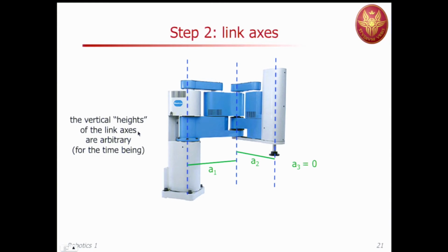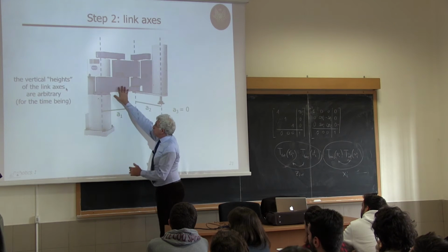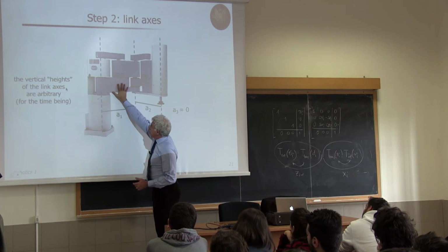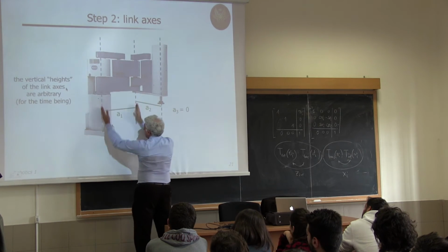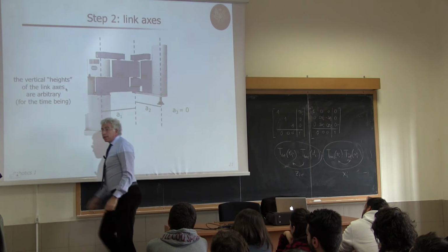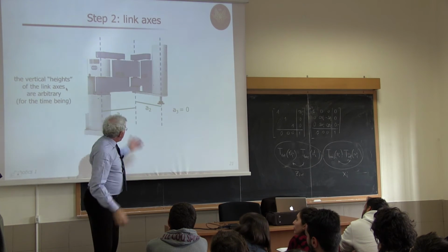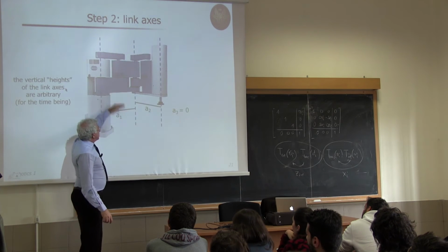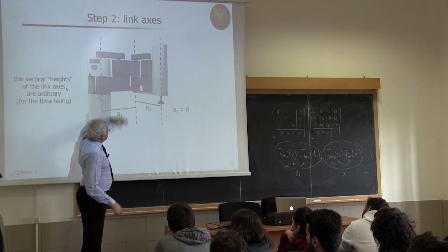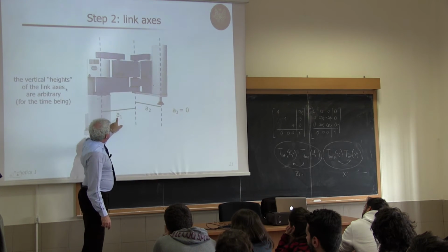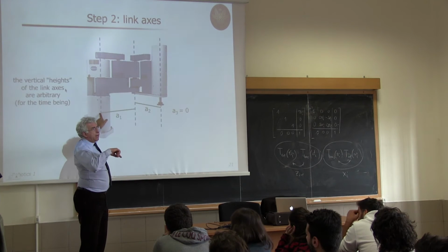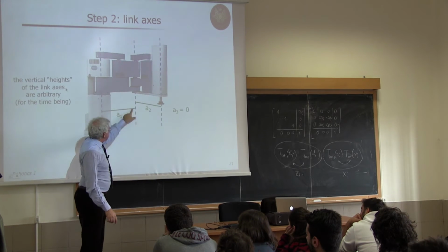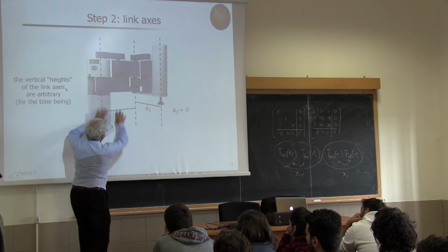The second step: look at the link axes. Now, common normal. This is link 1, joint 1, link 1, joint 2, common normal. These are parallel. There are infinite common normals, but A1, the length of the link, is uniquely defined. So I can place the x1 axis at whichever level I wish, but then when I compute A1, it's this distance. It will carry a sign depending on how I choose xi, but this is defined. So I'm just placing it generically here.